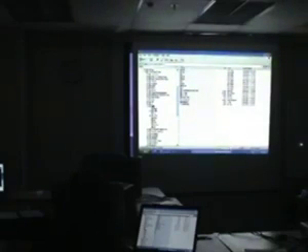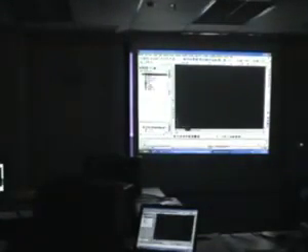Civil 3D is drawing based, so the only thing you need to do is back up that drawing. Another major difference between Civil 3D and Land Desktop is that Civil 3D is very much object oriented. Land Desktop is just project based, right? But Civil 3D is object oriented, meaning if you move the horizontal alignment, the vertical profile is updated at the same time. So I'll show you what it can do.